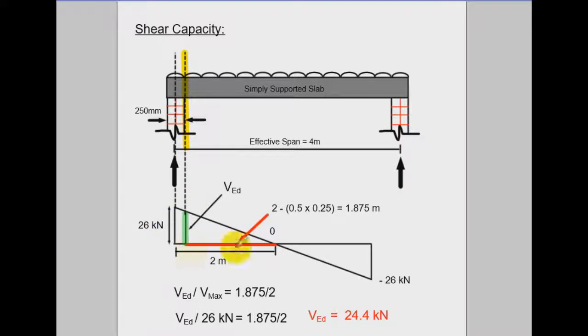And just draw the shear force diagram, and then that's what you need at a certain distance here. You have this triangle here, the small one, and you have the bigger triangle, this one there. So we have this distance, and this distance. This is the long distance over the short distance, or you can just take it the short distance over the long distance.